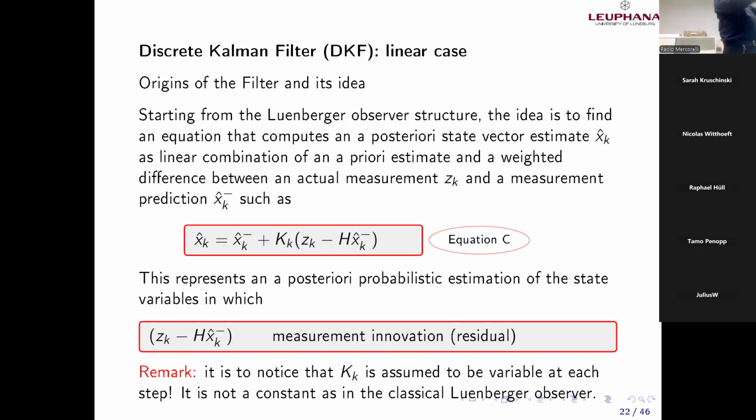Better to say, the correction of the approximation of the first step, which in the second step is xk hat, is put as a hypothesis equal to xk hat minus, what I know a priori, plus, look here, the parameters which change over time at each step, multiplied by, please pay attention, what I am measuring minus the corresponding estimated variable.